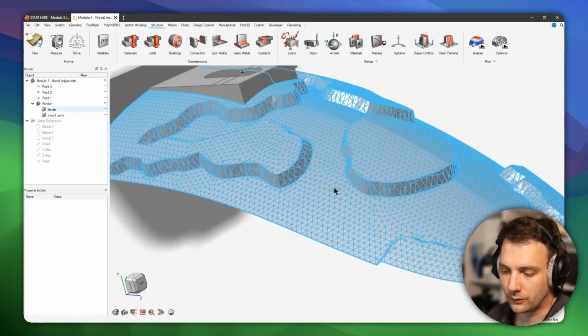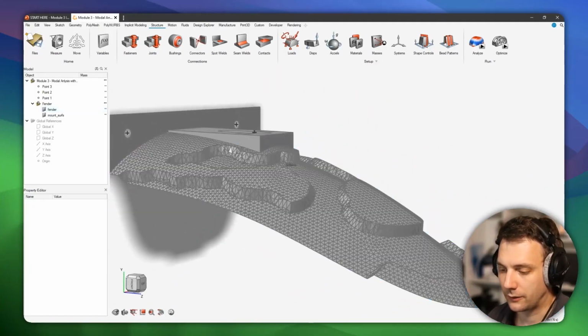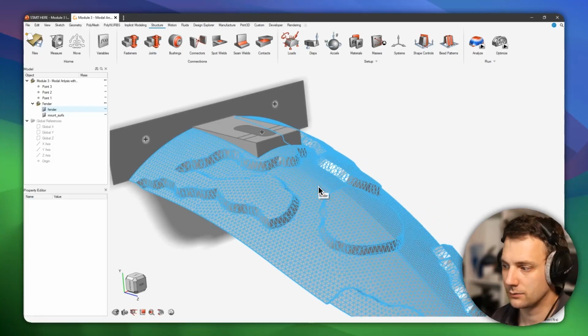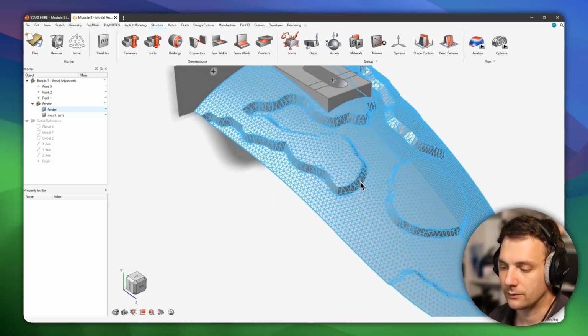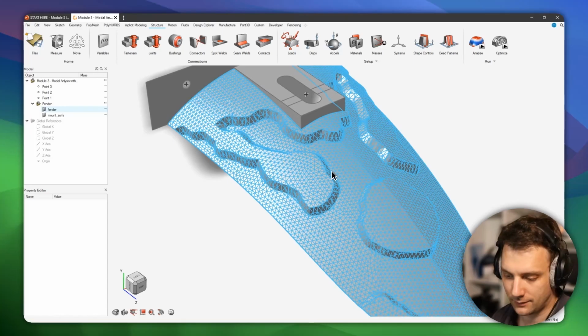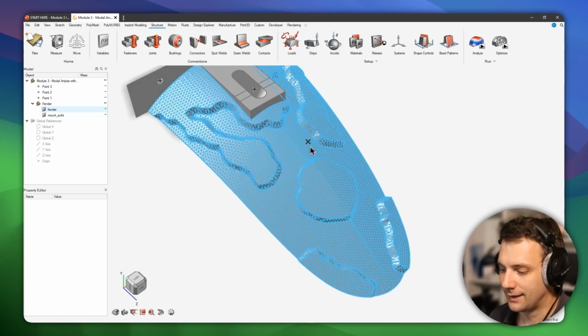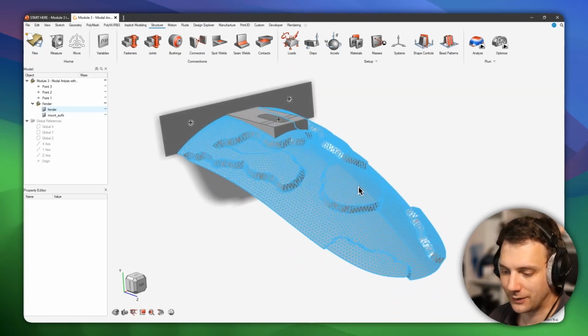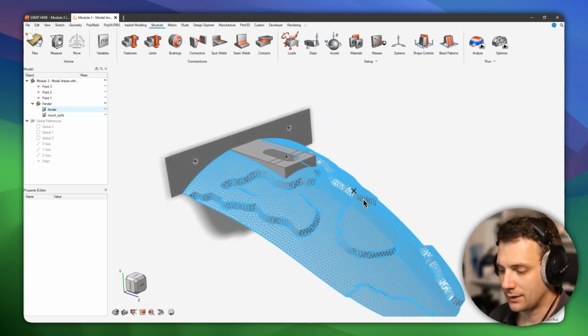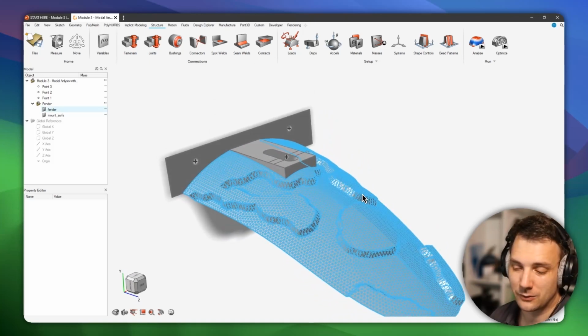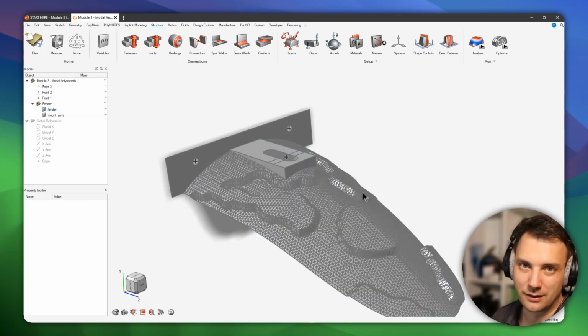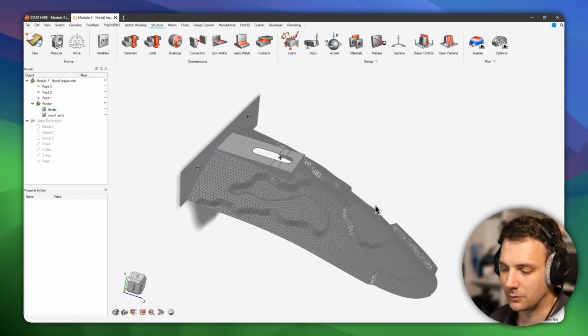And this is being used all over the place. You can see that, for example, on metal stair floors or something like that, or also every sheet metal in cars. So this is being done in the industry quite often. If you have a frequency problem, there should be a bell ringing in your head, screaming topography optimization, because that's a cool thing to do. You don't have to add too much mass, you just have to structure the part a little bit differently, change the geometry, and then you're mostly fine.